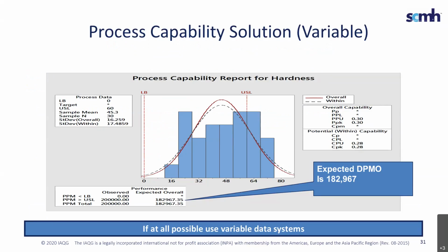So the fact is that you try to make sure that you can do one of two things. You try to make sure that you are going to have a capable process, and if you want a CpK of 1.33, one of two things. You either have to move it over the center so it's far away from the upper spec limit, I'm just using this example, or you have to reduce the variation that you're seeing. Either way, if you can't center it, lower bounds is a great example of that.